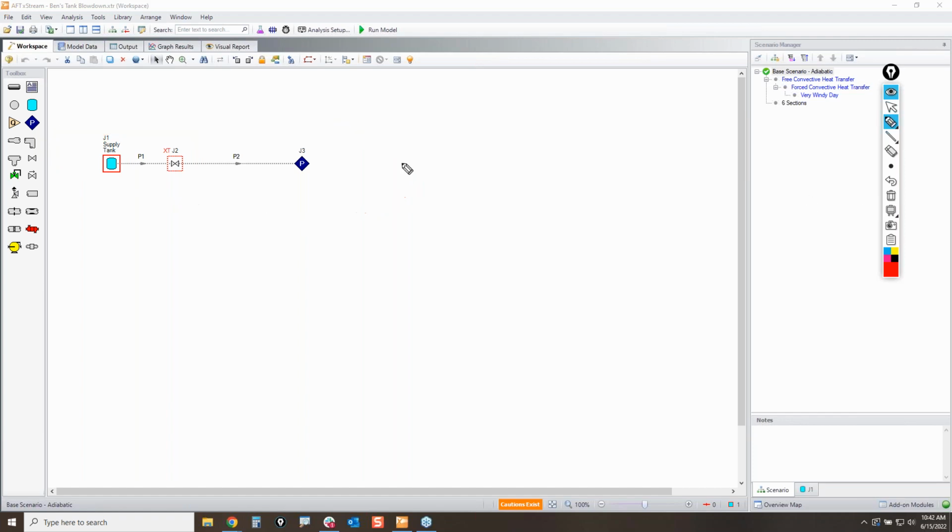What that means is if this is open to atmospheric pressure, in reality, we're going to be having air in this pipe. That's not being dealt with currently in any of our software, really. Right now, there's ways that you can kind of get around that and do a snapshot in time with Fathom and Impulse, but right here, in reality, you have air in this pipe, but AFT xStream is assuming that that's all filled with nitrogen already.